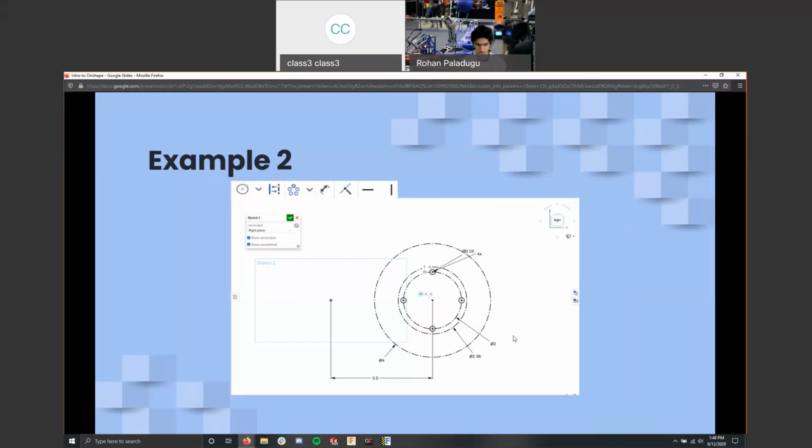And then I have what's known as a bolt circle in the center. This bolt circle is 2 inches, and it's essentially the 4 bolts that I want to use to mount the motor onto the plate that I'm going to be designing for this shooter. You can see that I used the circle tool and construction geometry to get my shooter wheel, my motor outer body, and my motor bolt diameter. Then I used the circular pattern, denoted by this dimension of 4x, to take my first motor mounting hole and pattern it around 3 more times to get the 4 motor mounting holes that I need.